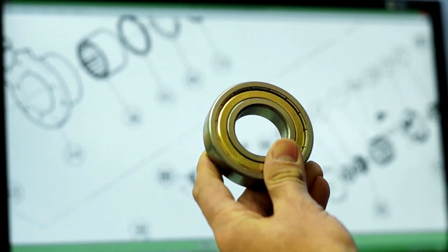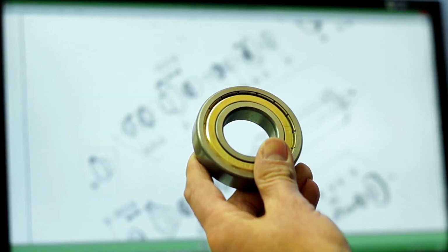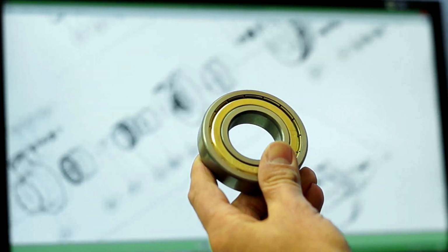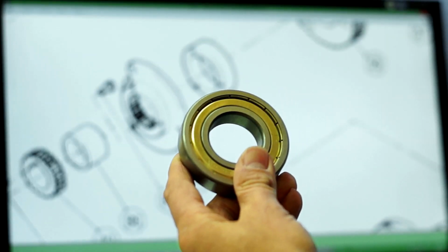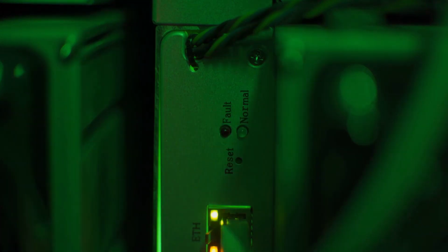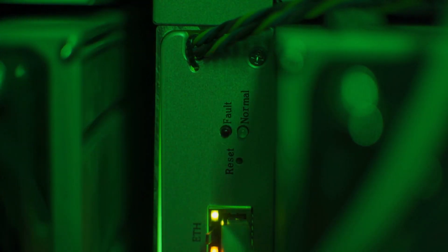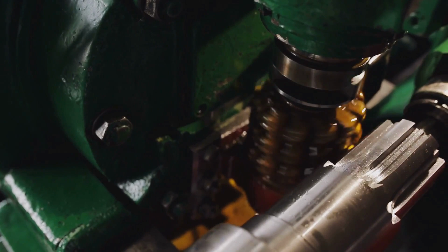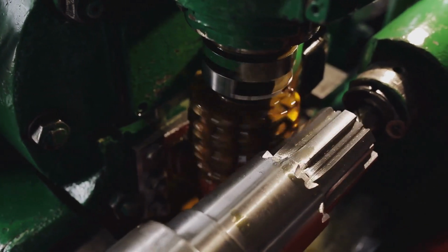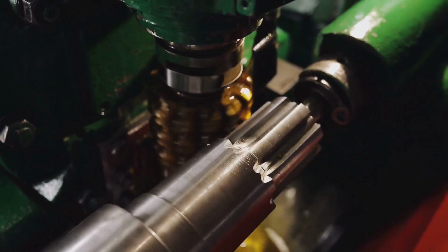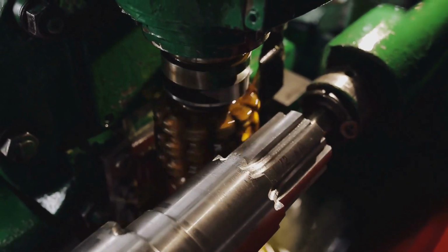Vibration analysis provides supporting details by detecting mechanical issues such as bearing wear, imbalance, or misalignment, which may be contributing to overheating. By correlating thermal imaging with vibration data, maintenance teams can distinguish between electrical and mechanical failures, ensuring precise diagnostics and effective corrective actions. This multi-technique approach enhances predictive maintenance strategies, reducing unexpected failures and extending equipment lifespan.